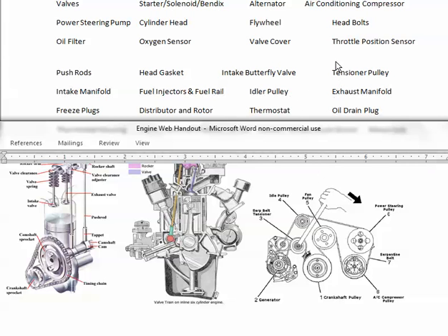So between these two words, I would definitely use them in relationship to the serpentine belt, and you can also use it in relationship to the other accessories. But there is an idler pulley actually on the tensioner arm. Its only job is to move in and out to keep the slack off of that belt.